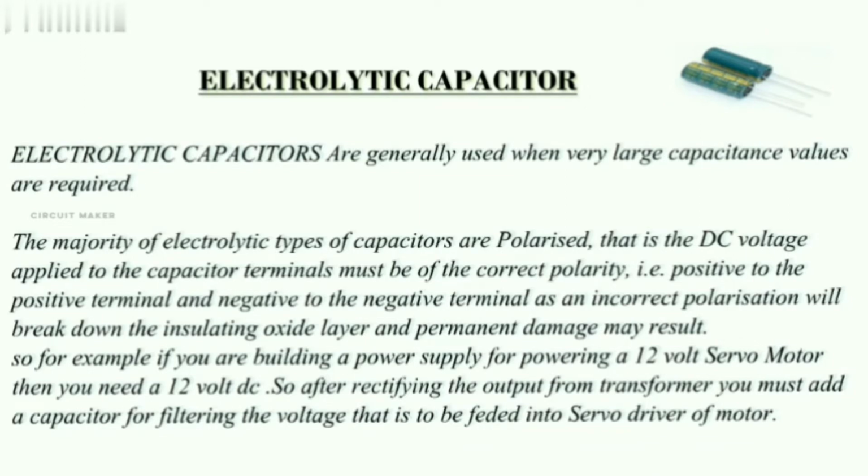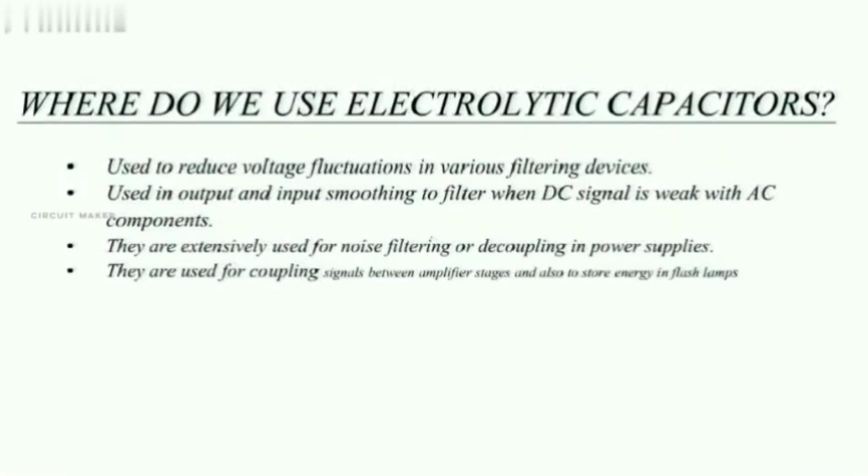Electrolytic capacitors are used for filtering the voltage and also used as couplers in circuits. They are mostly placed in circuits for stabilizing the voltage and filtering the supply. Electrolytic capacitors are used for filtering the power rails. If you analyze a power supply, you can see an electrolytic capacitor put across the output of the rectifier. It's because electrolytic capacitors can filter and clean out the AC ripples from the DC line and can deliver pure